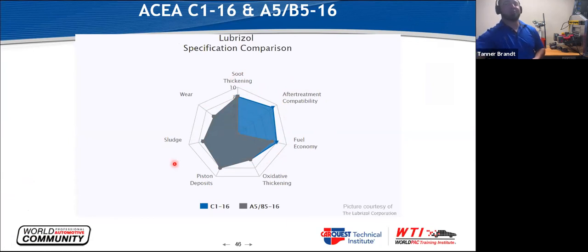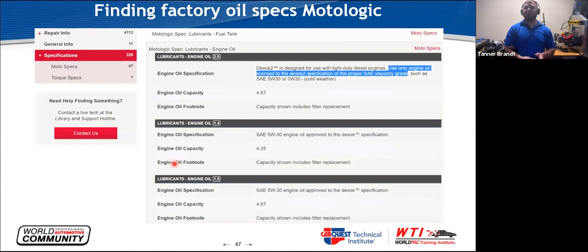I'm just throwing the name Liqui-Moly out there because a lot of people use that in European stuff. But say you're using the same Liqui-Moly in a gas car and in a Sprinter, even though it's good oil, you may not be using the right spec. So that's something you need to consider, so you're not creating failure of expensive DPF systems.